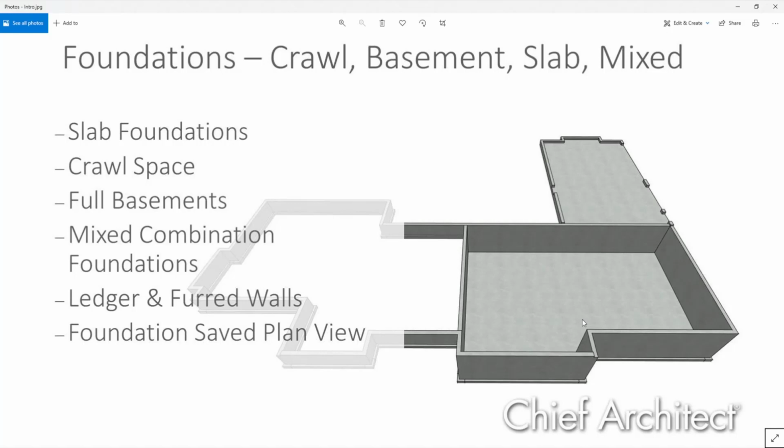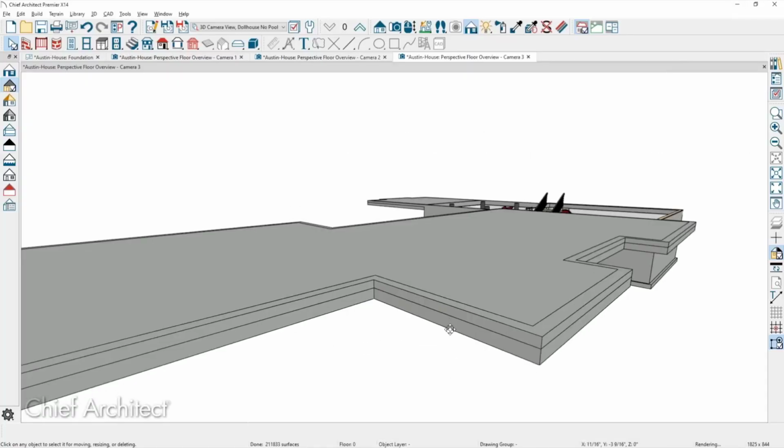I was wondering if there's a simpler way to address the whole thing, where all perimeter beams are grade beams, 36 inches deep, 12 inches wide, and a slab which is like 5 inches thick with a drop down at the garages and the porches. Right. So when you build your foundations, are you selecting use monoslab, or what are you using to build the foundation? Right, monoslab. On slab. Have you tried building it with a stem wall that looks like a slab? So this is what I've done in this case.